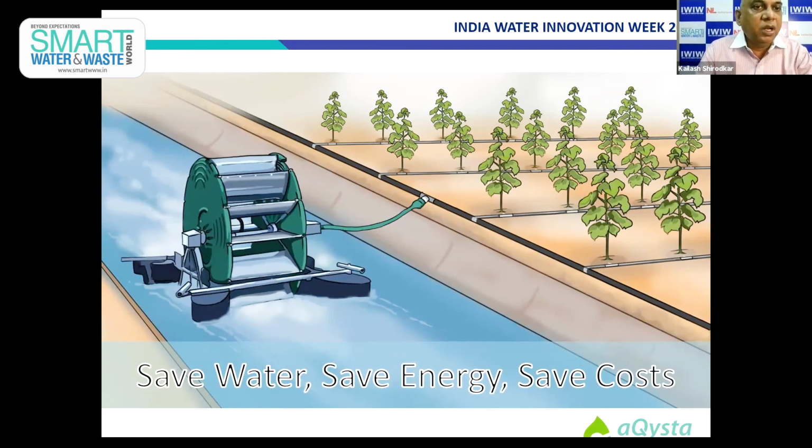One question, Rahul, is: is there any criteria to operate these pumps on a minimum water level of the river? Yeah, so the river needs to have a level of at least 12 to 18 inches. We recommend 18 inches minimum, but we've seen that it also works in rivers where the water level recedes below 12 inches. Just the water needs to be in contact with the paddles, if you've seen the picture. So shallow rivers, shallow streams, not a problem. Anything above 12 inches works.